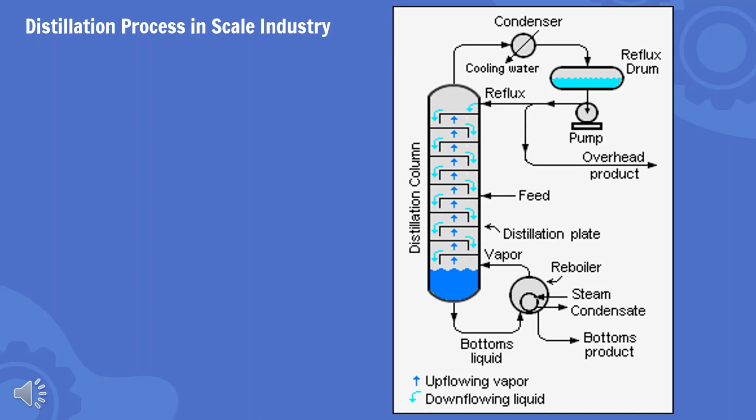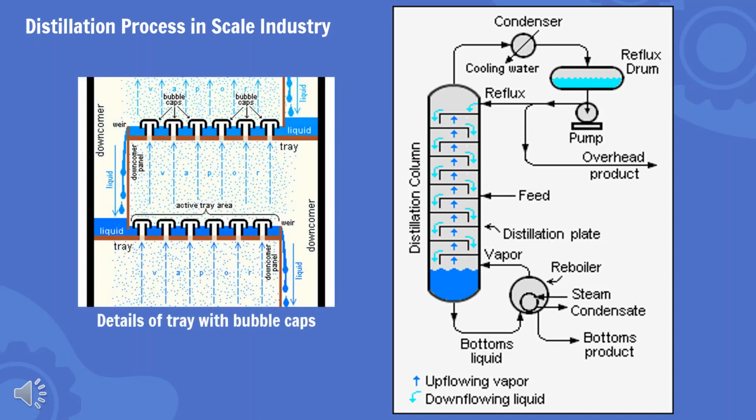At any given point in a fractionating column, vapor will be rising, liquid will be falling, and molecules will be mixing. Columns naturally have a certain number of stages, like the figure on the left. In every stage, there are bubble caps for holding the liquid as a product in every stage. However, the columns are designed to be tall enough to achieve a certain percentage of separation by finding the minimum number of required stages. Vapor reaching the top of the column, the distillate, is collected into an industrial condenser.